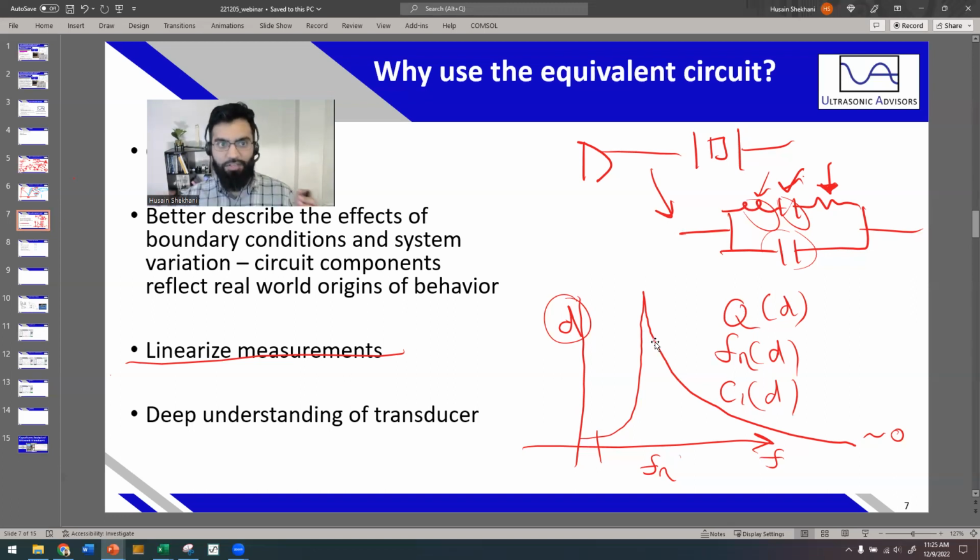Basically, at anti-resonance, you don't have much displacement. At resonance, you have a lot of displacement for a set voltage. So you have a different quality factor and a different system stiffness at resonance and anti-resonance. That's not going to play out very linearly. You're going to try to fit a model to it. It's not going to work. However, your impedance analyzer uses such a small voltage that it doesn't really matter. The displacement at anti-resonance and resonance are still about zero, even though the resonance is probably 100 times higher, 1,000 times higher. It's still about zero, because of the low voltage.